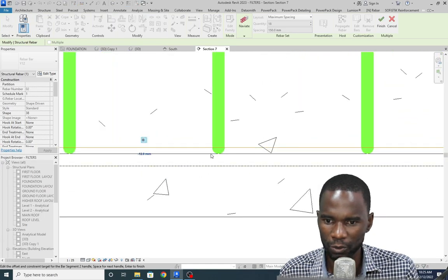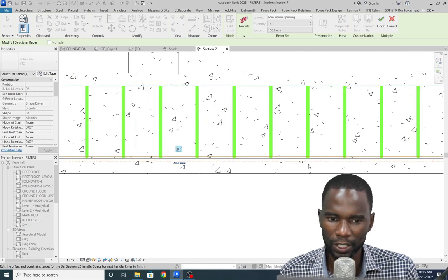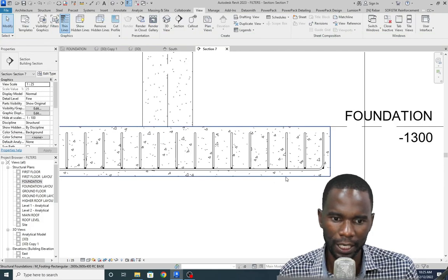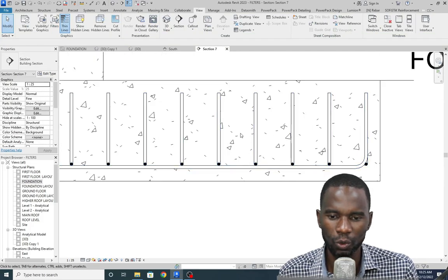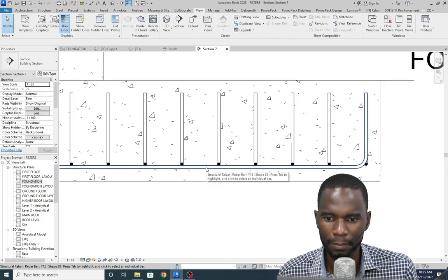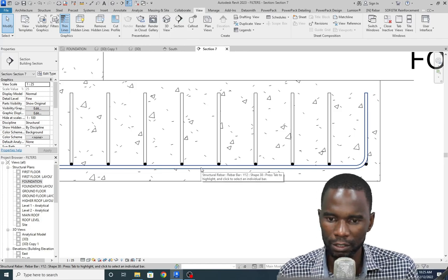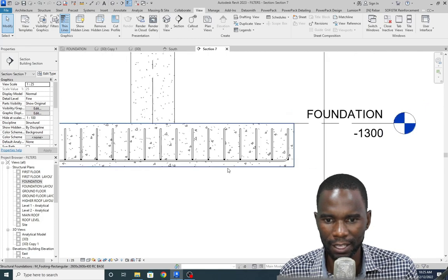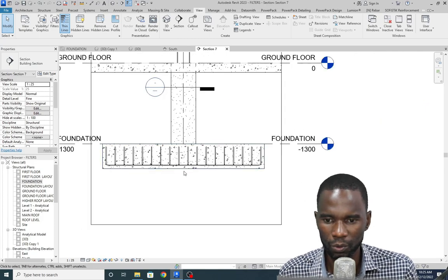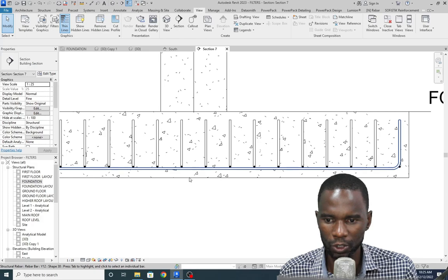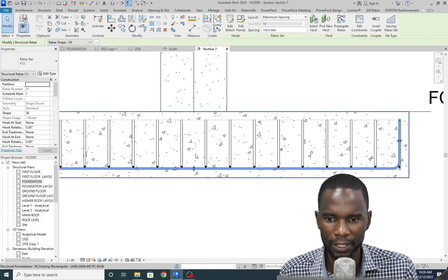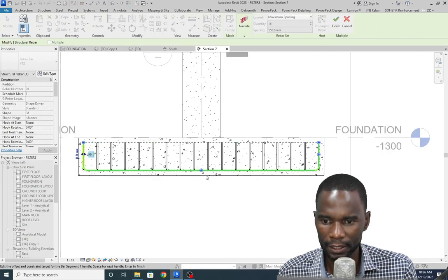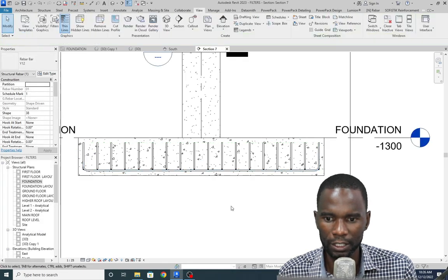You see that it's going to move like that. And it's sitting right on top of the other bar. Let me just click the green check mark. Click outside, as you can see sitting there. So what this means is that as the bar down there moves, even the other one on top will move, because it's constrained there. If I change the cover there, everything will move accordingly. So let me also constrain, I think, this bar down here. I think I did. If I just select that one there, it's 0. Then click on finish. I've constrained it.